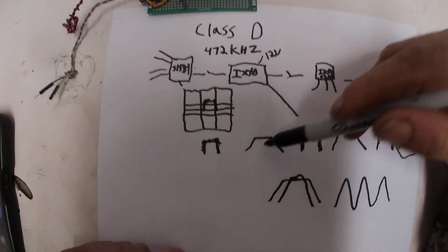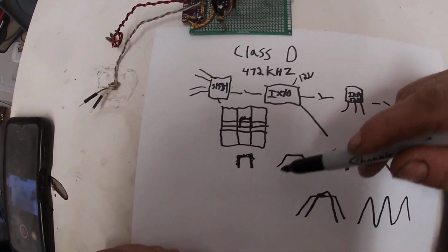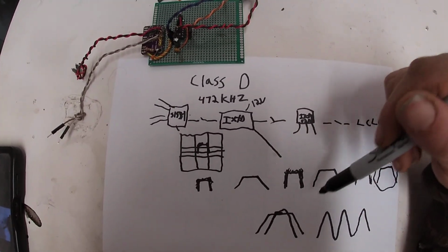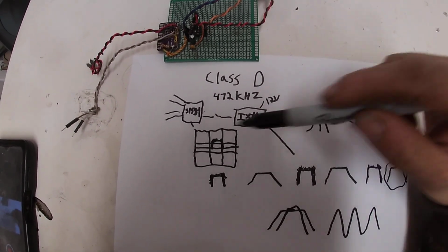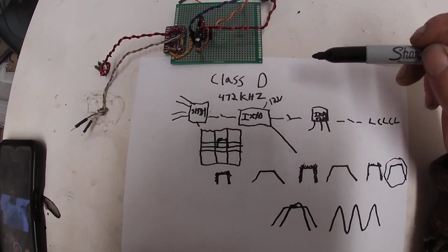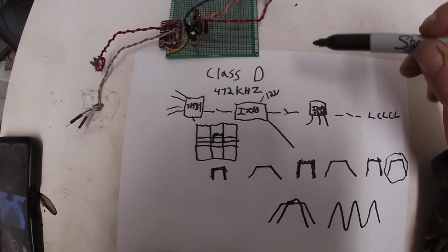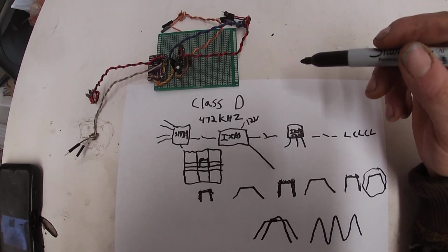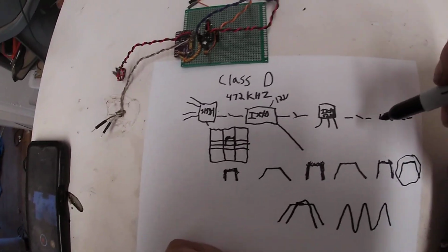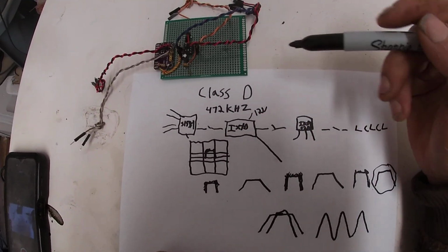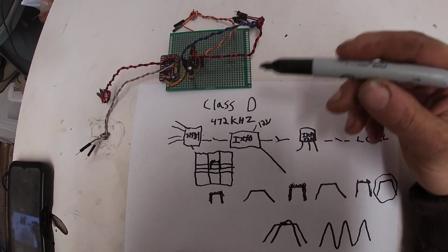Our resistors that just happen to make the square wave less fast on the edges are really there just to protect each device and just keep it actually functioning. But we make RF at the end, and that's why Class D can be so efficient.